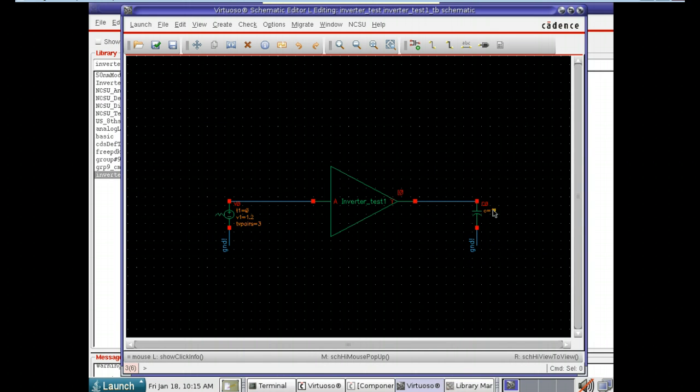So that's just a little trick to use. So just keep that in mind. That's a little more than our introduction right now, but just thought I would share that. Okay, so we do have our signal source set up, but as you can tell, we don't have any power to our PMOS or NMOS. Our PMOS doesn't have a voltage source. Mostly, we're concerned about our PMOS, so I'll leave that one alone. But what we're going to do is go ahead and build our power for the inverter.